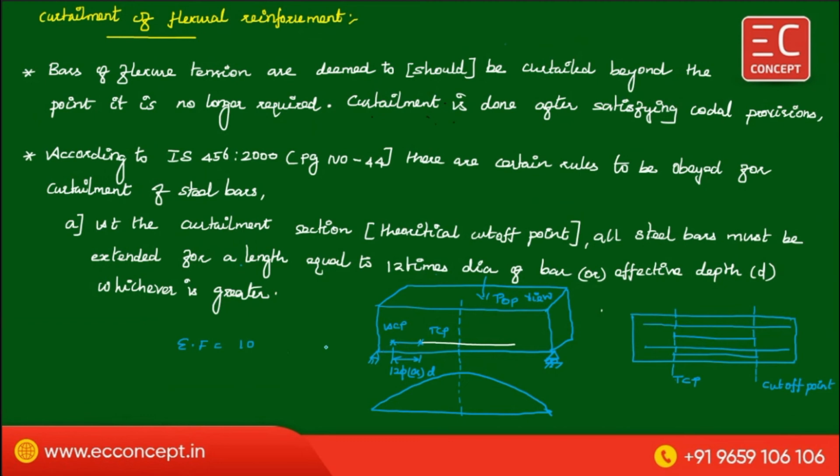You have to find out the shear capacity of this section, for example, 100. Let us take 100. Then what is two-thirds of this 100? That is 200 divided by 3, which we can write as 66.67. So 66.67 is the two-thirds, meaning you can allow the external shear force up to 66.67.